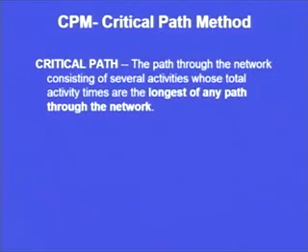These are 2 types of network solving methods, or we can say network solving programs. Now, the critical path method, as you already know, takes care of the critical path, and the program evaluation and review technique is also based on the same principle. Now, what is the difference between them? The critical path method is used wherever the time estimates for each and every individual activity are known with a certain degree of certainty.